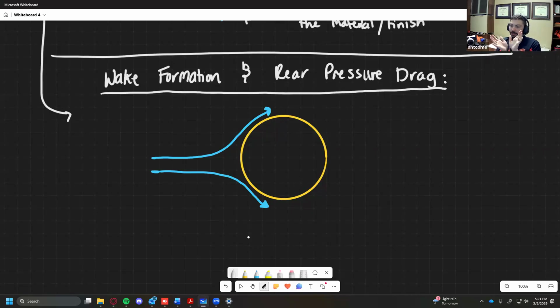But if you've all driven a car in the rain, you'll see the liquid climb up the windshield as you speed up, right? That in part creates beads of liquid which create these rough surfaces, which now more drag has to overcome. So my guess is that in the long term, the answer would be no, because a wet wing will ultimately become dry from flying, and during the process of drying will create streamlines of water, which the air now has to move. So I think the answer to that is no. It should be more draggy. But someone can prove me wrong.